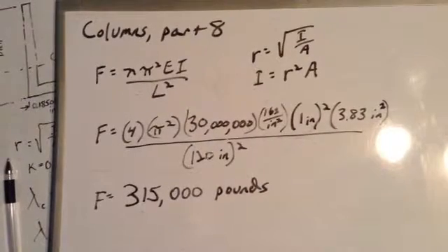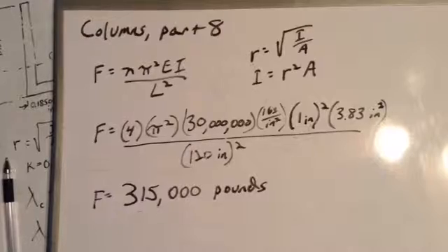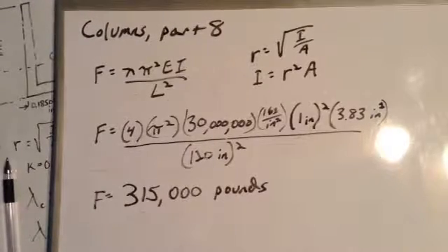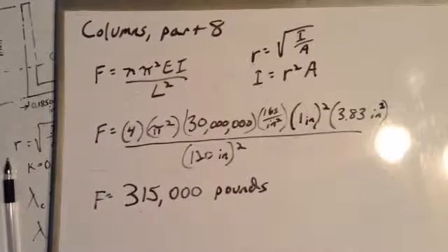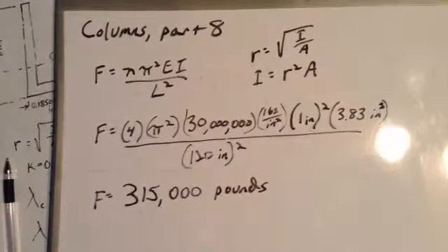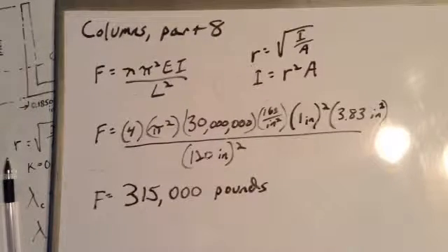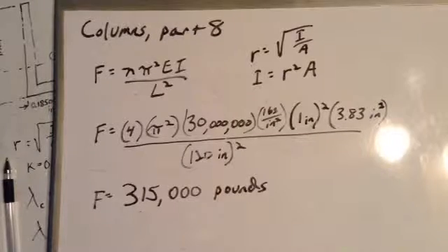What we do find by toying around with this calculator is that it's standard procedure to allow short columns much lesser loads than the theoretical Euler equation loads. Now, short columns are allowed much greater loads than long columns are allowed, but still they're allowed way less than what the Euler equation calculation will turn out to be.